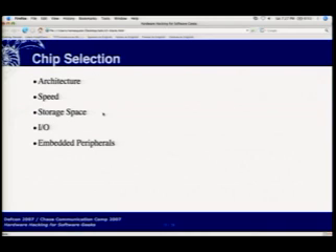So the chip I used for a few projects is the ATmega 168 made by Atmel. It's a 16 megahertz system clock, 16 kilobytes of storage space, just flash on the chip. It's programmable pretty easily with variants of C.